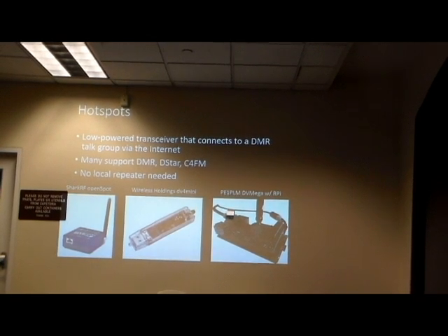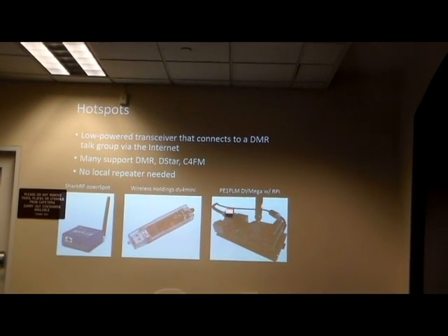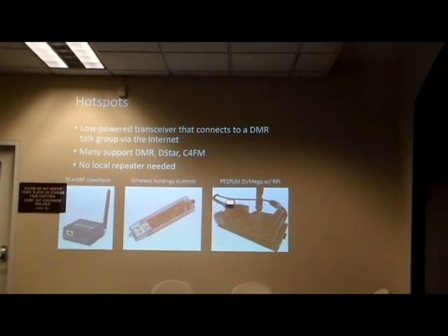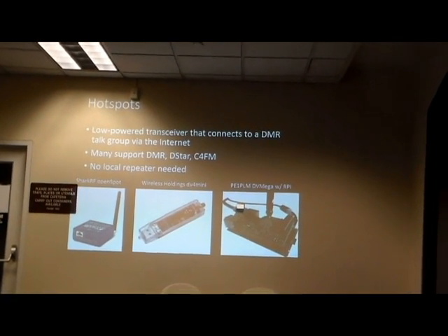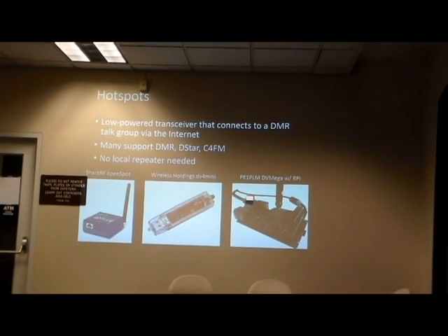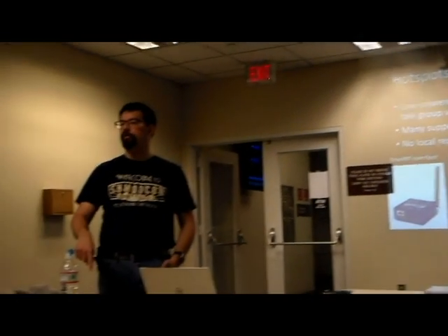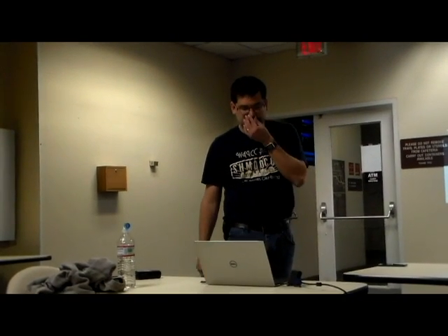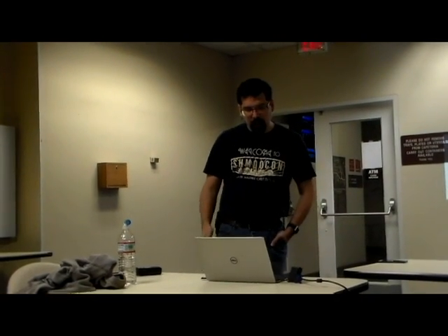The big thing about hotspots is they don't actually understand what audio is at all. They generally just pass packets. Your radio is the one that has the codec, taking your voice and putting it into digital information, and then these just pass the digital information out. You still need a DMR radio to interface with them.